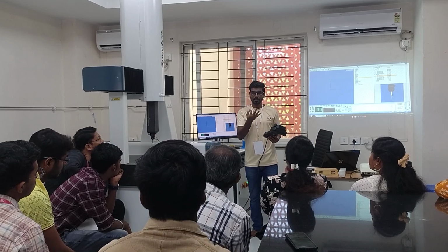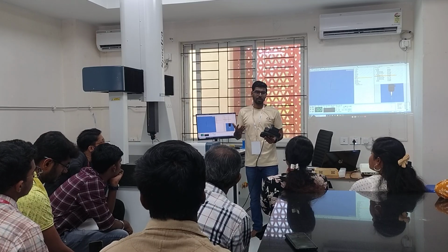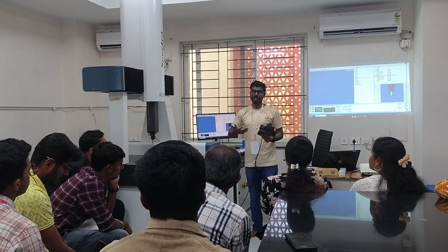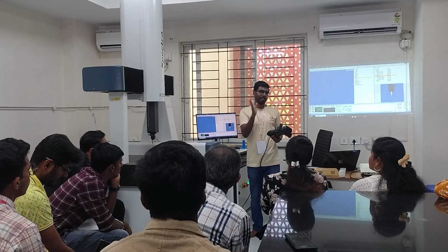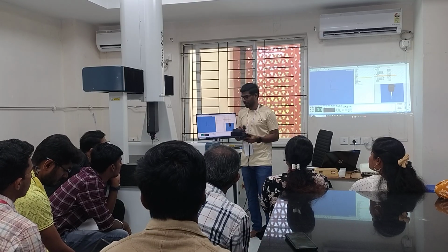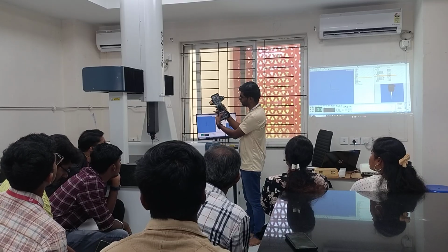If there are 3 points, what is the planarity? Will it be equal to 1, or might it deviate? Planarity or flatness, you can say flatness. If you are using 3 points, it will be totally, perfectly flat. So for this, I'll take more than 3. I'll take 5. So first of all, I have to engage.